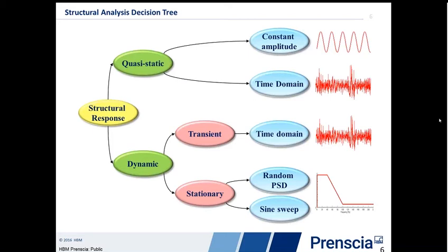We also can look at the dynamic domain. And the choices there are really us trying to capture the overall physics of the problem. Obviously, we're going to take the simplest approach, the one that gives us the most reasonable answer. When we have load frequencies that start to interact with the natural frequencies of our structure, we're forced to take the dynamic route. What we're going to need to do is put the loading into our FE analysis and run some sort of dynamic analysis to capture the structural response.